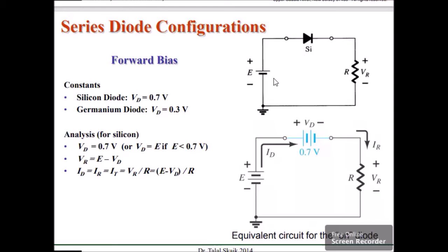You determine the flow of current, dun lumalabas yung current sa positive side ng ating potential. Kapag dumaan siya dito, same siya ng arrow sa ating diode, ibig sabihin on. Then, pag nag-on na, you determine kung ilan ba yung voltage drop niya dito. Kapag ideal diode to, walang nakalagay na silicon or germanium, zero to. Okay, kasi ideal.